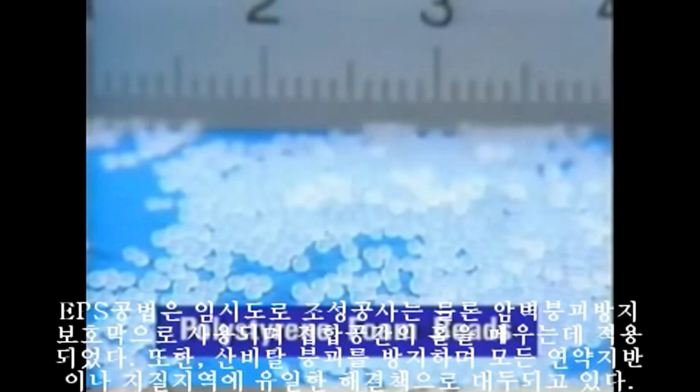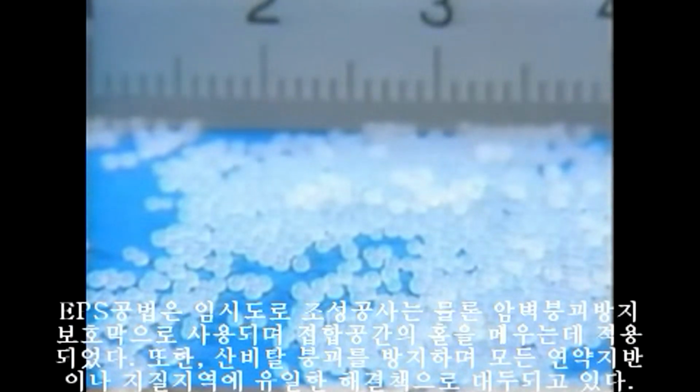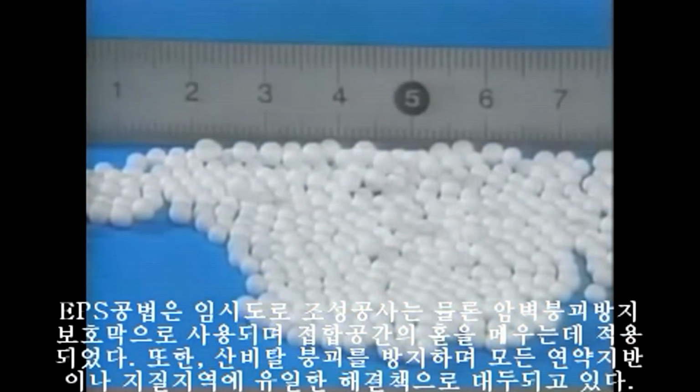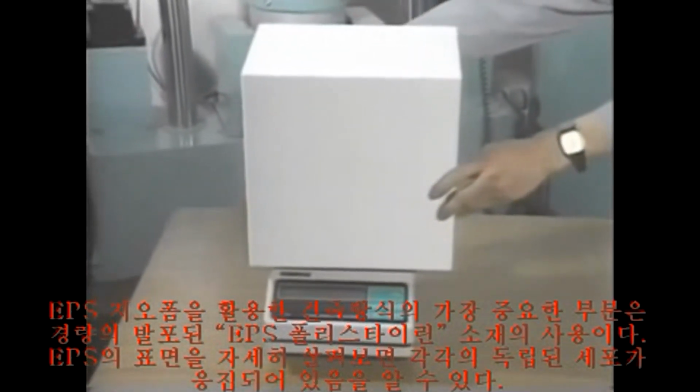The main advantage of the EPS construction method is that it makes use of the extreme lightweight of expanded polystyrene. If you look closely at EPS, you will see that it is a collection of very tiny individual cells which are 98% air. The weight-to-volume ratio is phenomenal, about 1% the weight of sand.